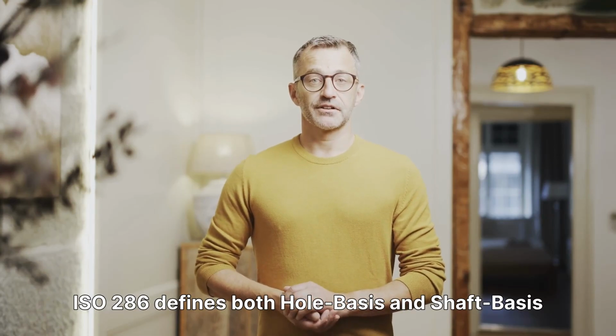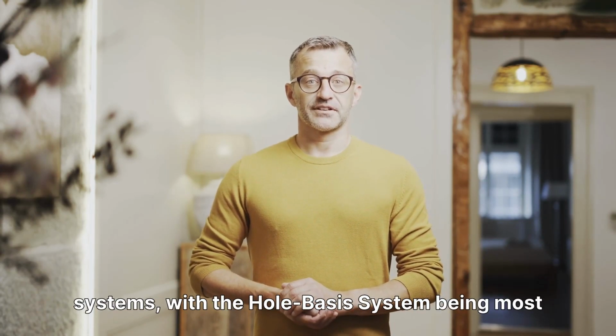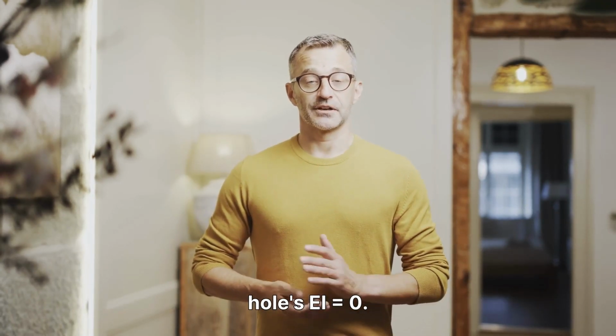ISO 286 defines both hole basis and shaft basis systems, with the hole basis system being most common due to easier manufacturing when the hole's EI equals 0.